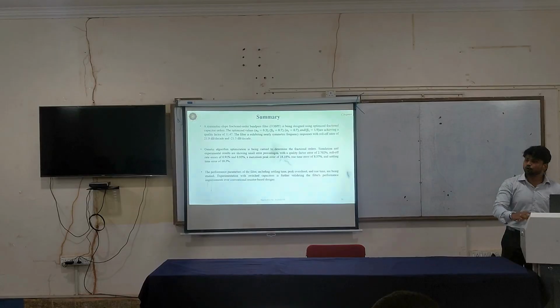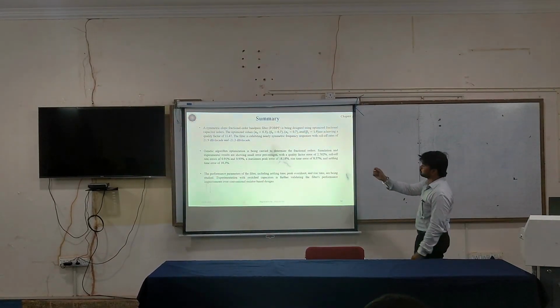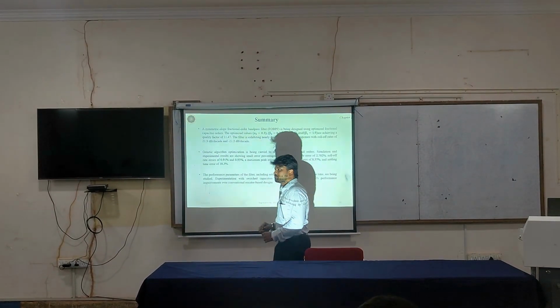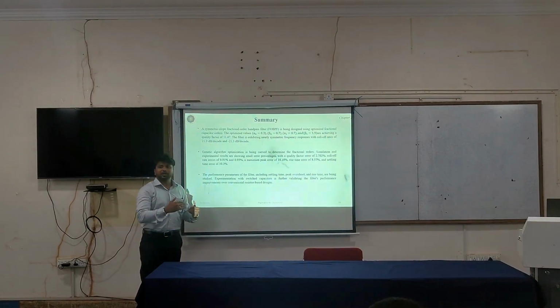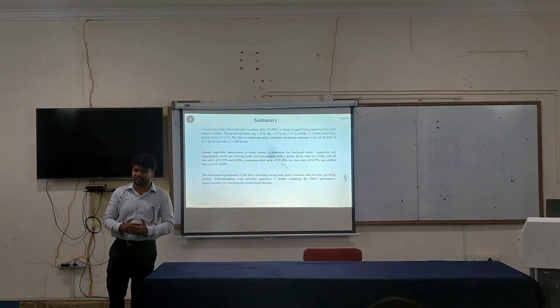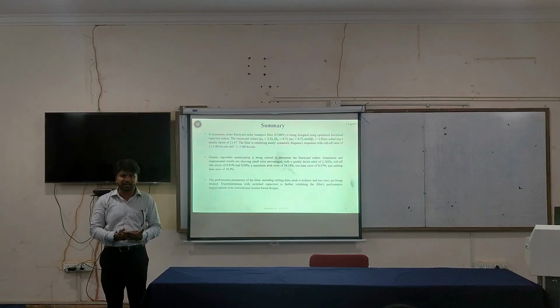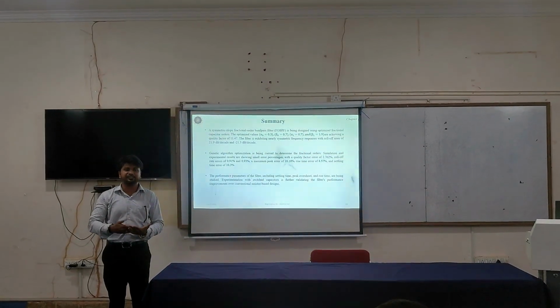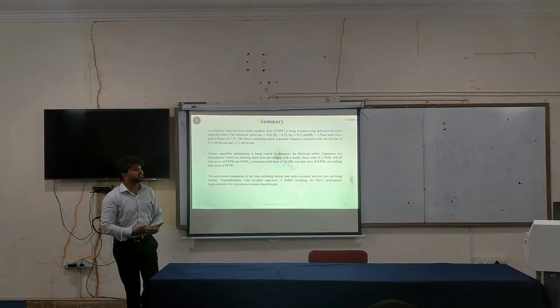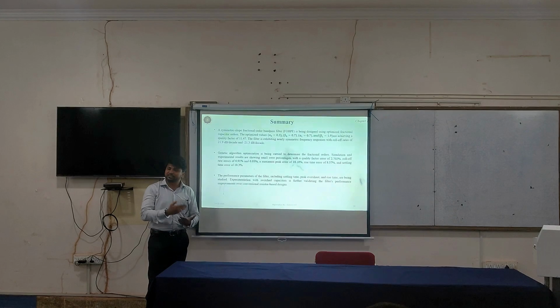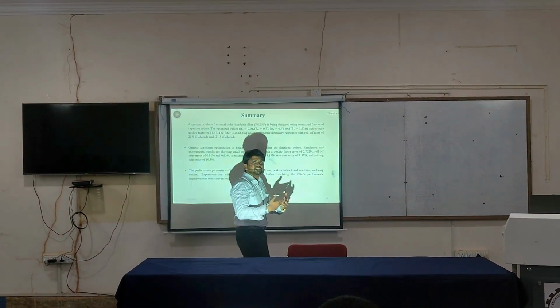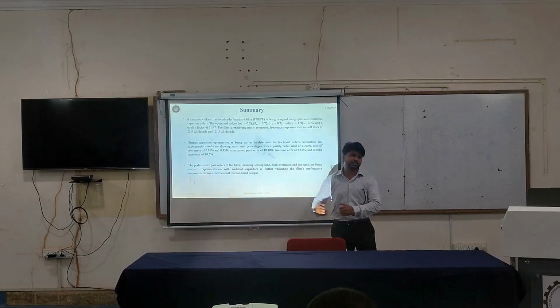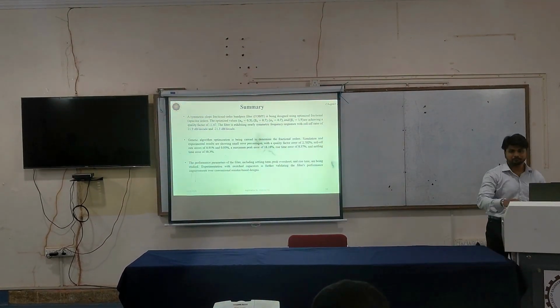Now, though this filter has a low settling time, still this settling time is high. Therefore, in order to improve the settling time, that is decreasing the settling time, decreasing the roll-off rate, decreasing the maximum peak, we are replacing the capacitor with a fractional capacitor in the switch capacitor. That is, we are using a switch fractional capacitor in our upcoming chapter, that is chapter 3.